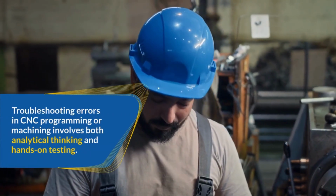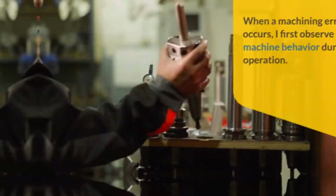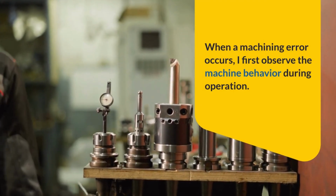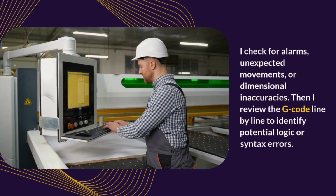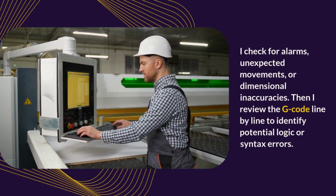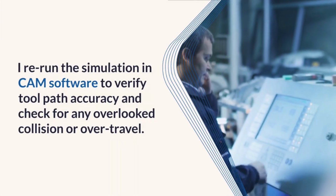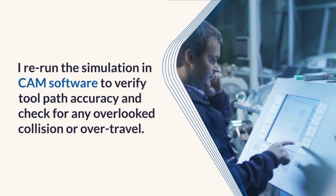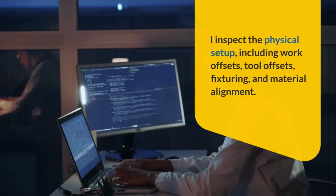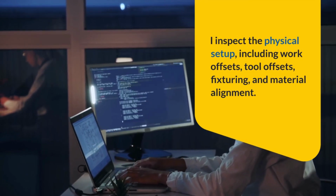Troubleshooting errors in CNC programming or machining involves both analytical thinking and hands-on testing. When a machining error occurs, I first observe the machine behavior during operation. I check for alarms, unexpected movements, or dimensional inaccuracies. Then I review the G-code line by line to identify potential logic or syntax errors. I rerun the simulation in CAM software to verify toolpath accuracy and check for any overlooked collision or overtravel. I inspect the physical setup, including work offsets, tool offsets, fixturing, and material alignment.